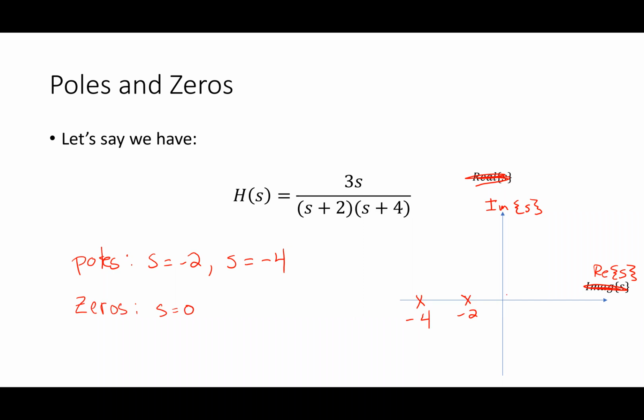So to show those, I draw a little O right there. Isn't that kind of redundant? Isn't what redundant? A zero is zero. Well, it's not always going to be the case. So what we're going to find is that different circuits have these poles and zeros. And when I have poles, I get things that are low pass in nature. All right. We're going to talk about that meaning in a second. What a pole and a zero are, basically, are the points where that function goes to infinity or where that function goes to 0. All right. And we use that term a lot.